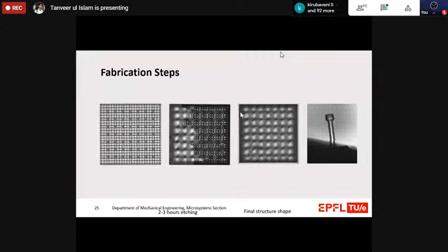Right now, because we are using fused silica, we can make almost any type of microfluidic devices or microstructures, because this has the application of generating nanogratings. Apart from that, the waveguides that we can make out of this are also being used in different applications. The third one is voids, where we can do ablation of the material, which has an application in making different devices, electronic devices and all. It is very useful because you have the flexibility of making three-dimensional structures with good resolution.